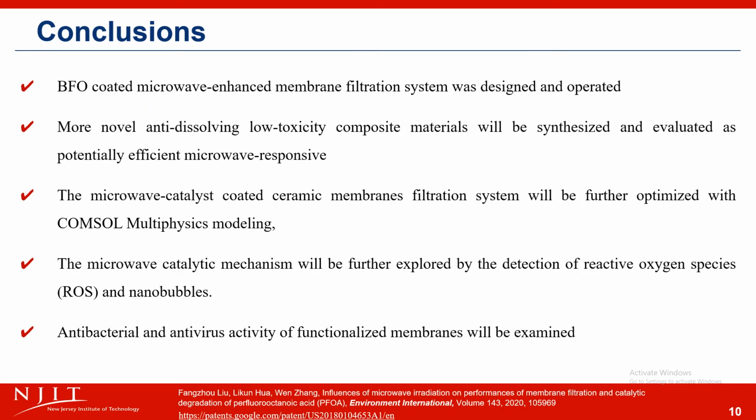Here are our conclusions. A BFO-coated microwave-enhanced membrane filtration system was designed and operated. More novel anti-dissolving, low-toxicity composite materials will be synthesized and evaluated as potentially efficient microwave responsive catalysts. The microwave catalyst coated ceramic membrane filtration system will be further optimized with COMSOL Multiphysics modeling. The microwave catalytic mechanism will be further explored by the detection of reactive oxygen species, or ROS, and nanobubbles. Antibacterial and antiviral activity of functionalized membranes will be examined.